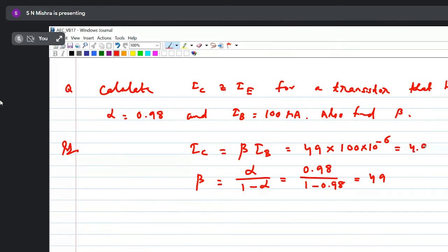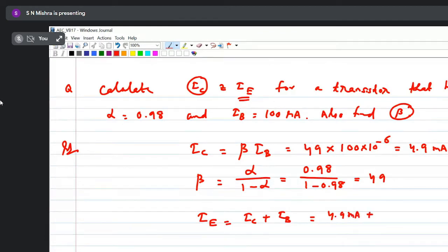So when I am passing lambda 3 from this input, it will be reflected by this fiber Bragg grating and circulated to the next port. So from this port, we are getting lambda 1, lambda 2 and lambda 3, a combination of lambda 1, lambda 2 and lambda 3.